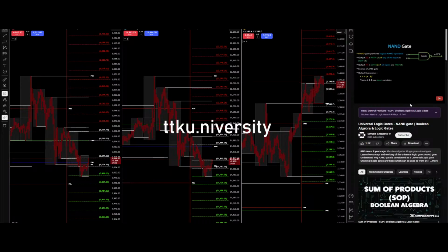Now the symbolic representation is as shown. Now you can see the NAND gate is pretty much similar to the AND gate symbol, but here we have a bubble at the output line. Now this is a 2 input variable NAND gate with single output Y, which is equal to A and B the whole complement. Here's the truth table. We have input values A and B. So we first calculate the AND operation between these two variables A and B. And since it is a NAND operation which is opposite to the AND, we take a complement and get the final result in the last column, which is given by A and B the whole complement.